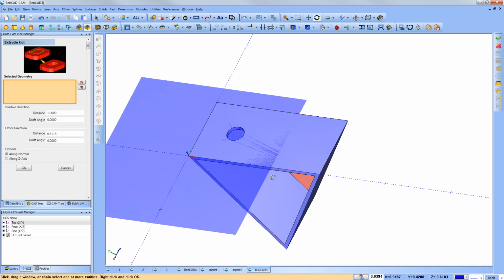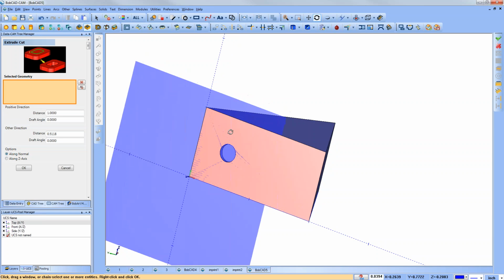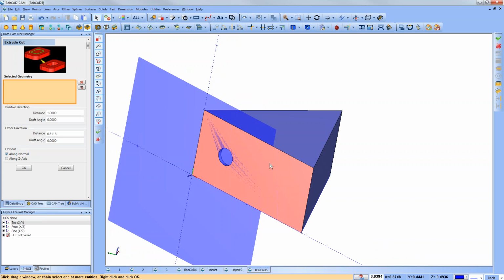And then turn the shading off. So now I've used two different functions. Now I'm creating a more complex part. A lot of the time you would be creating geometry using these functions back and forth. I used an extrude boss to create the initial triangle, then I used a shell feature, and then I used extrude cut.